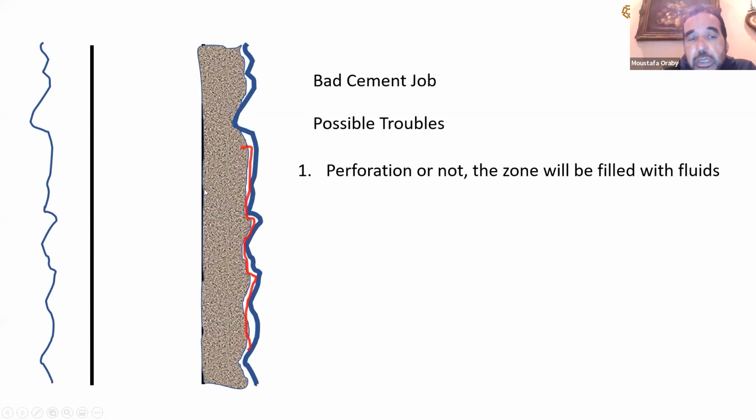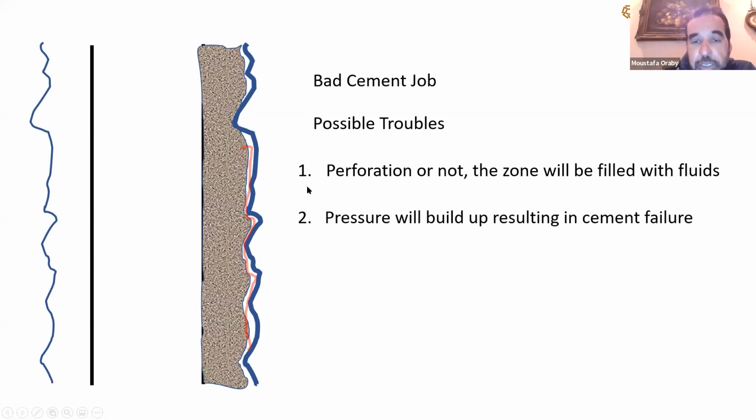So it is regardless of whether it is between the casing and the cement or the cement and the formation. Anything wrong in the cement is really a big issue, and we all like to avoid this from happening. Pressure will build up, the well will be under really bad condition, and disasters and unsafe things may happen in the wellbore.